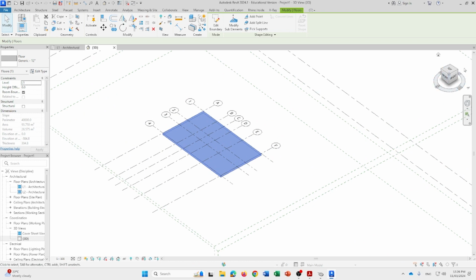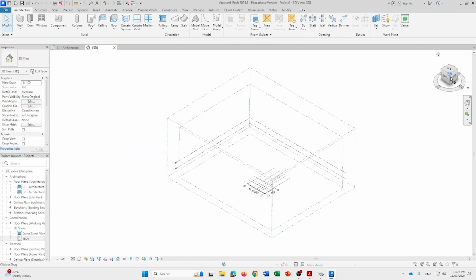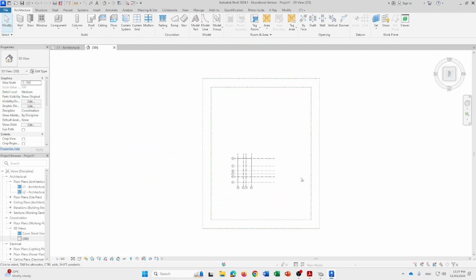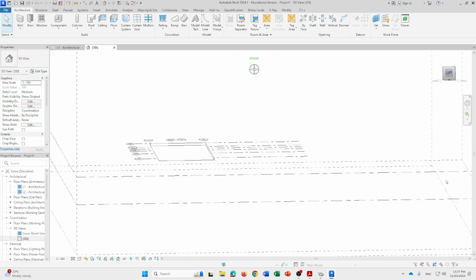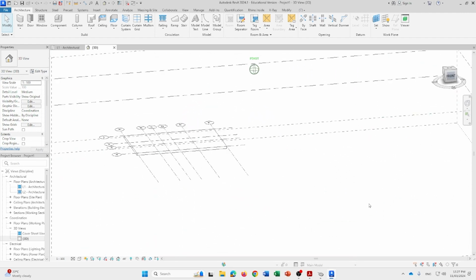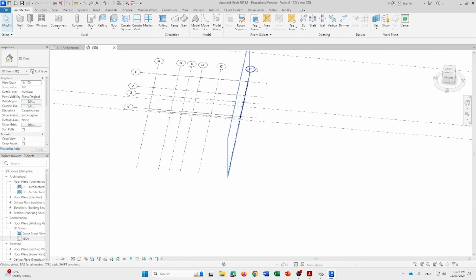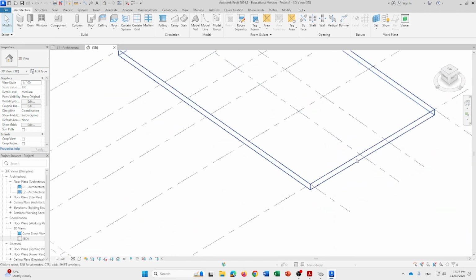Alternatively as well, we have our view box at the top right-hand side of the main viewport. We can actually click on this box and set the views as need be. So you can set up AXO views, elevation views, plan views in 3D as well. You can also hold down the left mouse button and move as is, and this will snap to the different views on the view box as well. So hopefully by this time we should all have a floor in place.